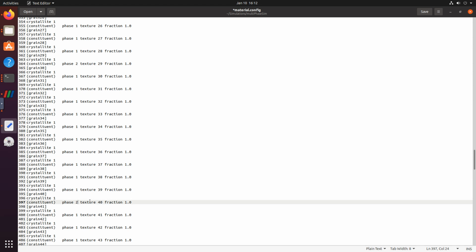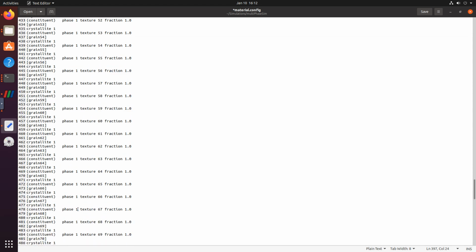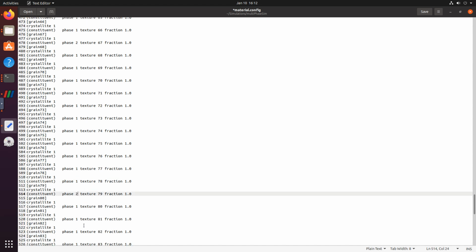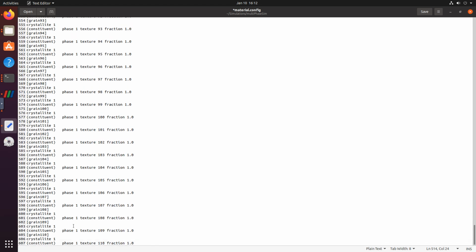But later, when we have actual materials, when we have their volume fractions, we do not do it like this. We use, for example, a software like Dream 3D to artificially create exact grain sizes and grain proportions and their positions that match with our material microstructure, right? But here I'm just trying to recreate this example with another phase, and I'm just randomly assigning them different values, right? And then, for example, I will go here, I will just define this too and this too, saving this.